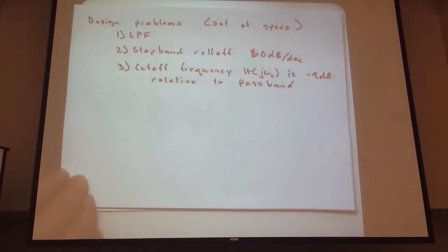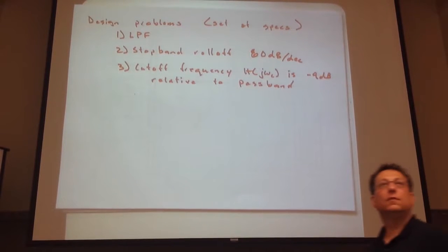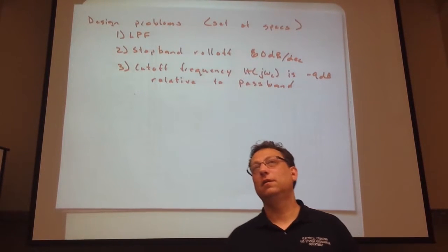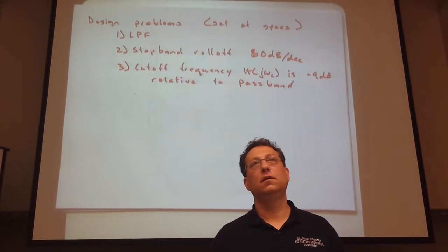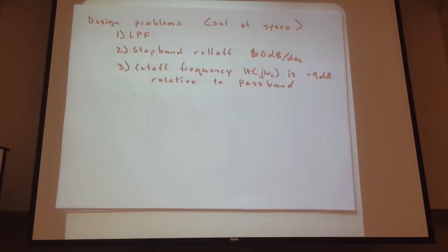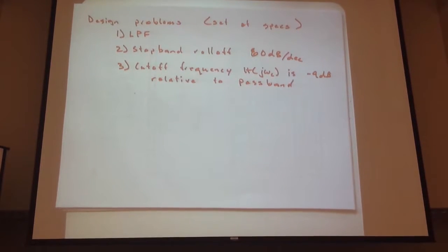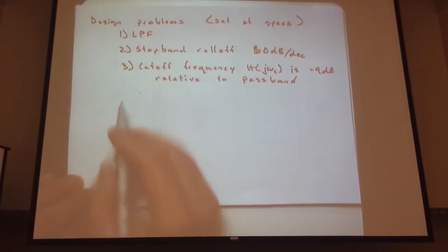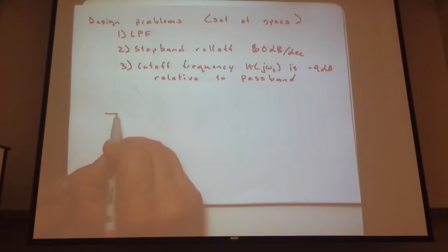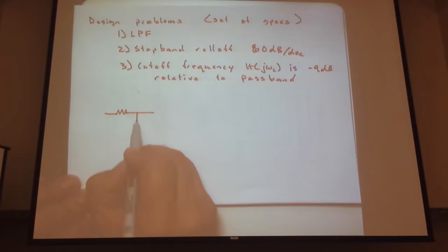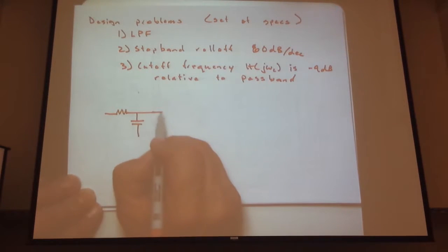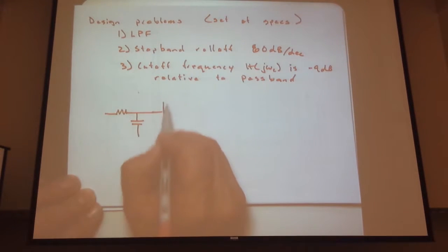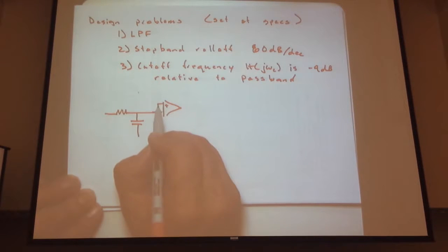How could you build this? That's one way of doing it, 3 first order filters. So what do we need in between though? Isolation op amps. Voltage followers.